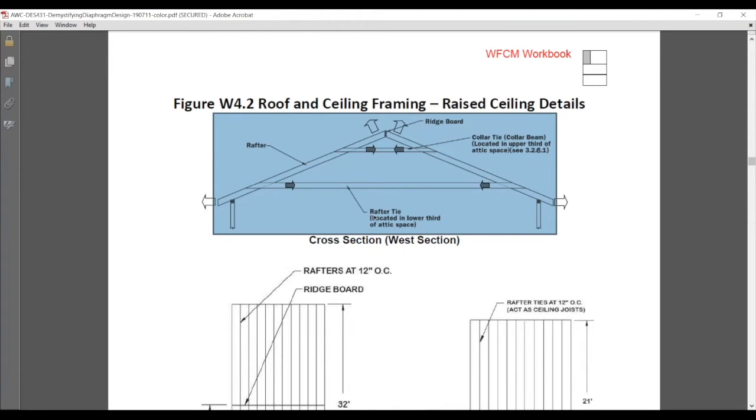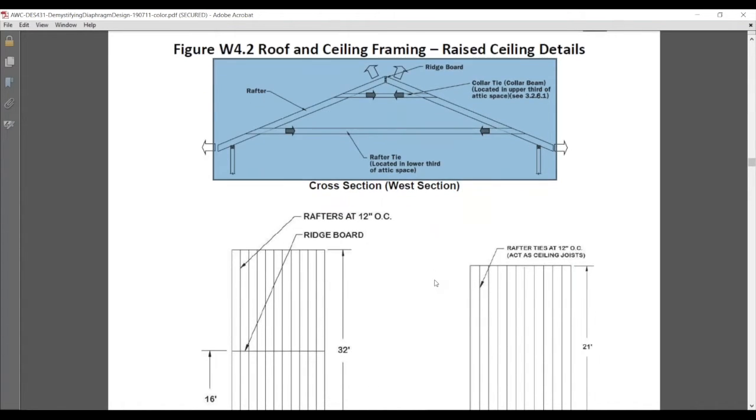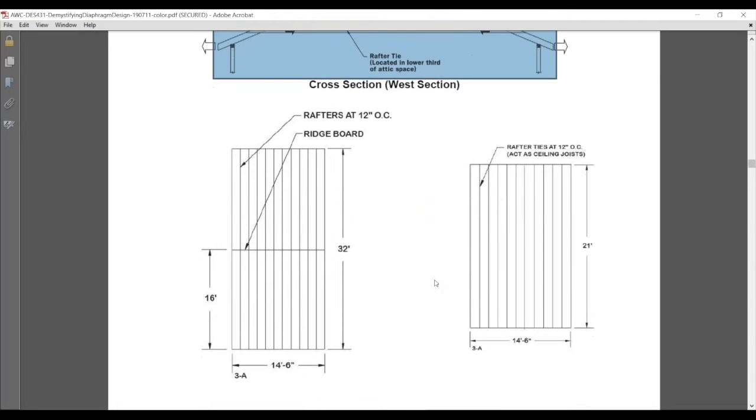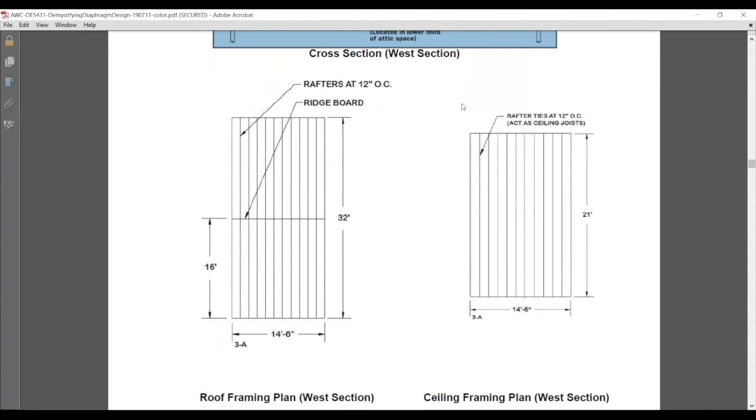And notice also that we don't have a windward and leeward wind load on these diaphragms. We're going to have just either a windward or leeward load, whichever is the worst case, but we won't be doubling up on a windward and leeward load for these two different diaphragms. So we'll talk about that and some of the adjustment factors you can use to help out in that process as well.